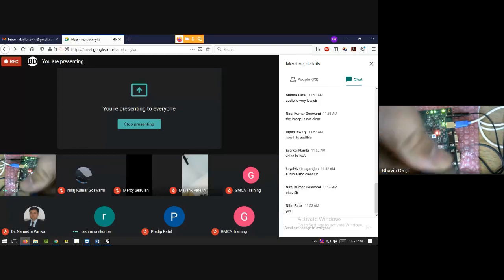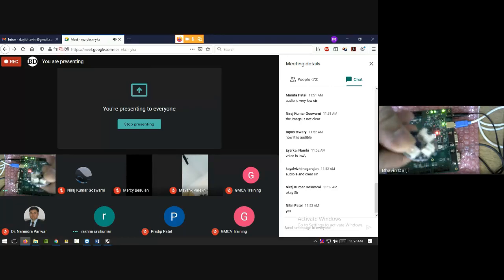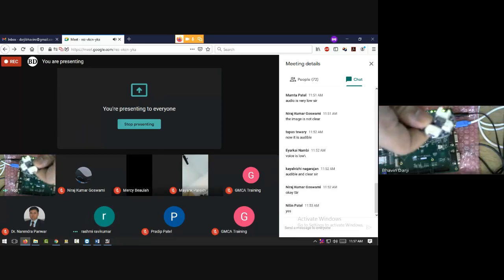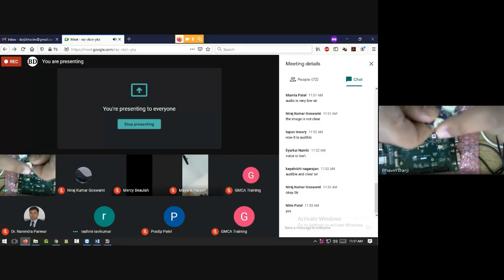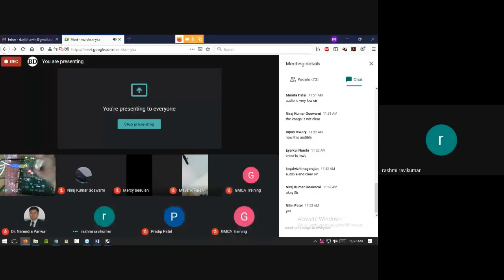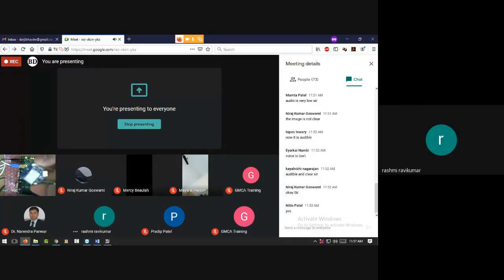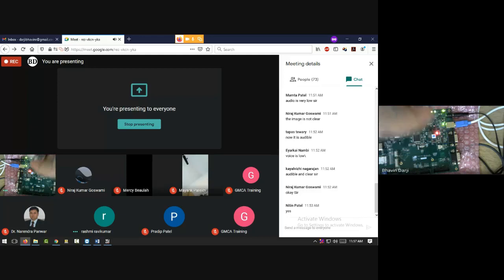I think you guys can see, correct? This is another microcontroller which is battery operated, and there is Wi-Fi also available on it. As you can see, there are three different connectors. This one is the battery connector, and these are GPIO connectors and an SPI I2C connector, and you can even use UART also. So instead of using Node MCU, you can use this kind of device. It requires less space, so you can go for it. Even you can use Node MCU also.